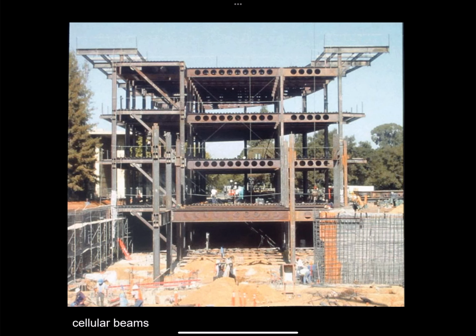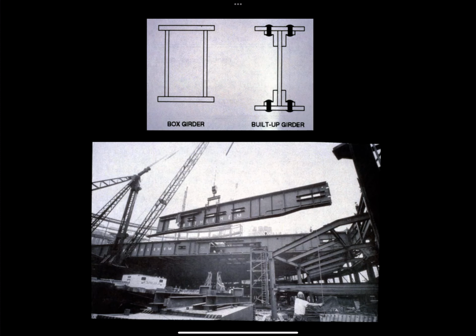Then stepping it up a notch to do even larger structures, we can do welded plate steel components. So these are not hot rolled steel sections. These are much larger, and these are all made by welding together steel plate to make, for example, bridge girders or highway bridge or railway bridge structures. And you can see that this girder that's being lifted into place has all the holes for services pre-cut in it, prefabricated, and can simply be craned into place.